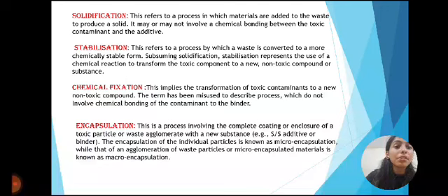Stabilization refers to the process by which waste is converted to a more chemically stable form. Chemical fixation involves the transformation of a toxic contaminant to a new non-toxic compound. Encapsulation is a process involving the complete coating or enclosure of a toxic particle or waste agglomerate with a new substance, additive.